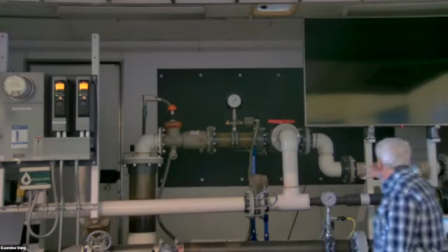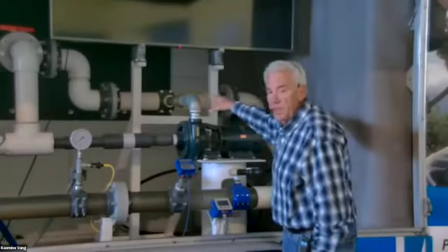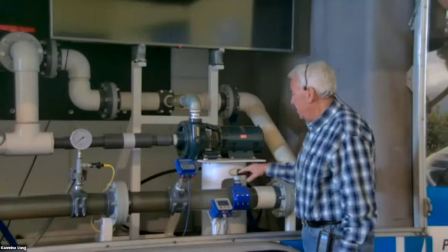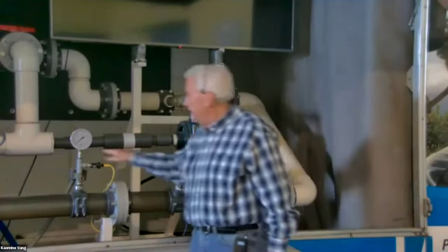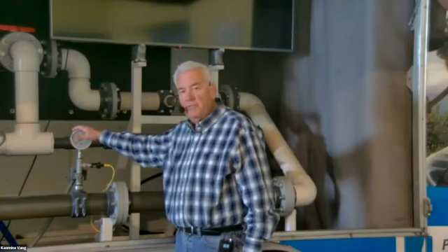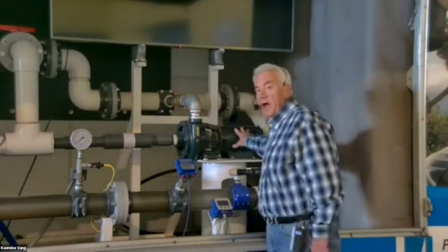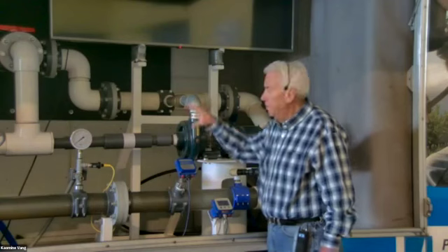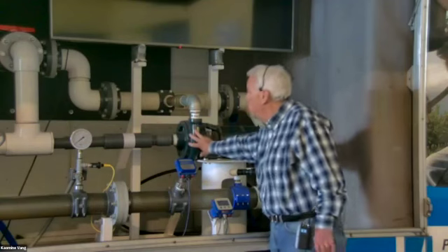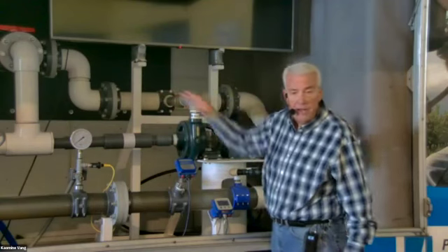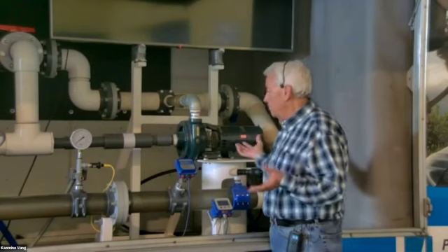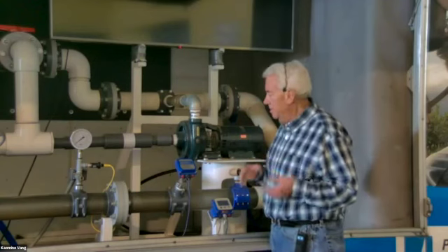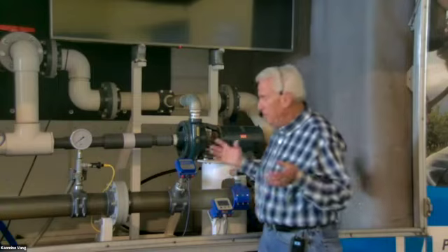Water comes on down the curve here as we move down, comes around the corner like this, and then comes back, and we have a second pressure gauge here. This is if we're running this booster pump right behind me here. I can divert the water and run it through the booster to create extra pressure. So we can see how much more pressure is being created by this pump versus the pressure being created out of the other pump. That's called a booster pump or end suction centrifugal pump, horizontal centrifugal. It's got a few different names anyway.